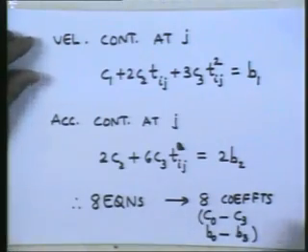So you would see that the user has specified at this stage only the initial position and velocity, and the final position and velocity, but at all the intermediate via points he has only required the position in which the end effector should move, and the system has chosen appropriate velocity such that the velocity and acceleration are smooth at the interface via point j. So we are able to do a curve fit essentially using again cubic polynomial segments, between 0 to Tij in the ijth segment and the jkth segment. So, 2 cubic polynomials in this case.